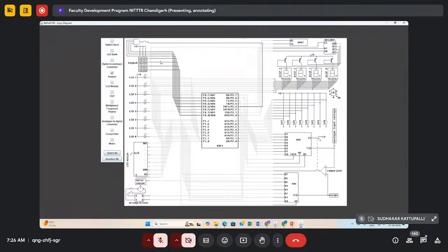Right. So in the actual keypad, how it works is they have connected a pin. They work on a row basis. Like suppose there is row 1, 2, 3, 4. Row 1 takes care of button 1, 2, 3. Row 2 takes care of button 4, 5, 6. In a similar way, right? This is connected to VCC. Suppose I'm pressing 1. So VCC will get connected to the pin to which this row is connected, right?